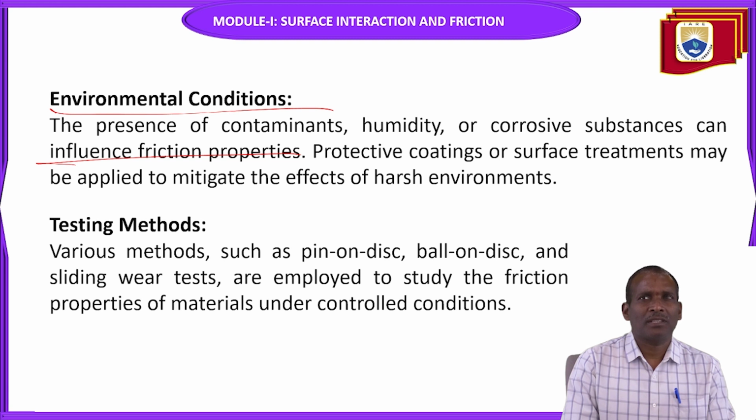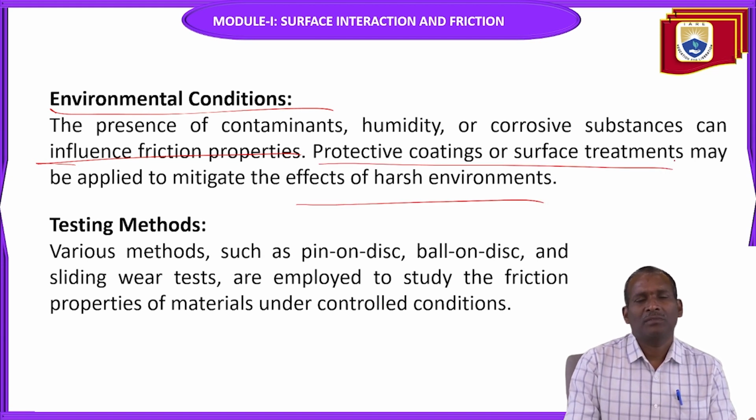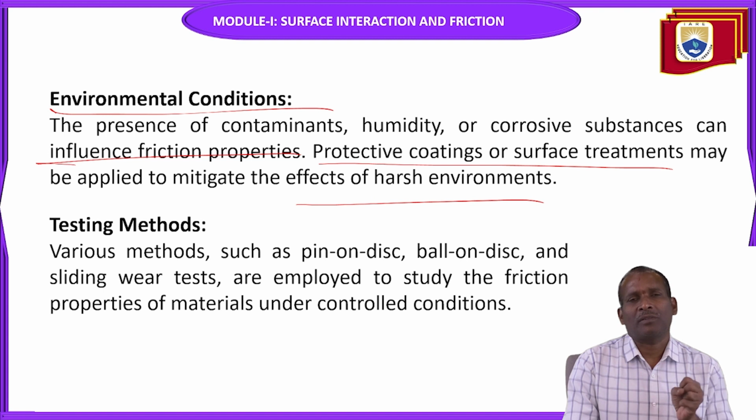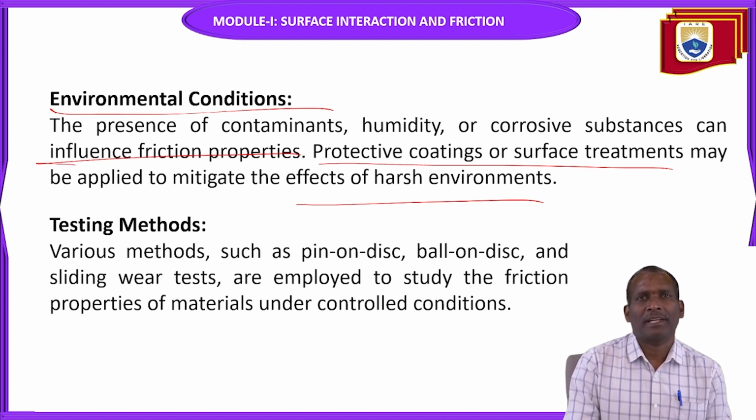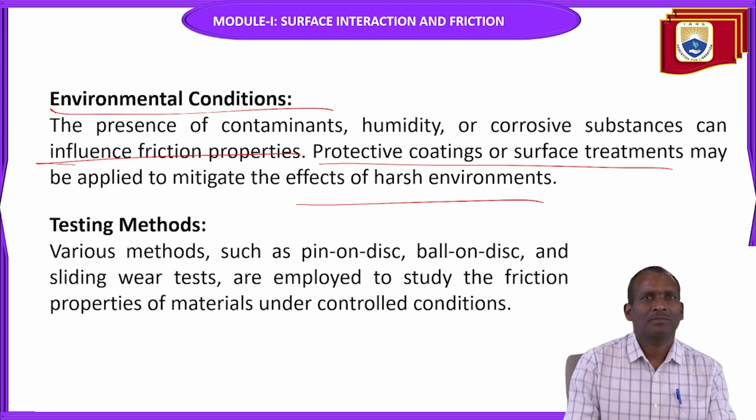Protective coatings or surface treatments may be applied to mitigate the effects of a harsh environment, to eliminate these factors: contaminants, humidity, corrosive substances. Surface treatments may also be applied to reduce the friction. All these come under environmental conditions.